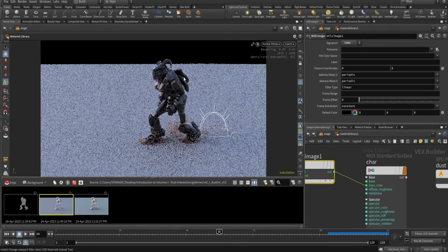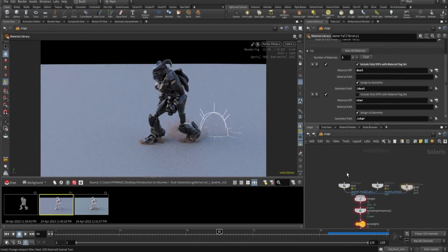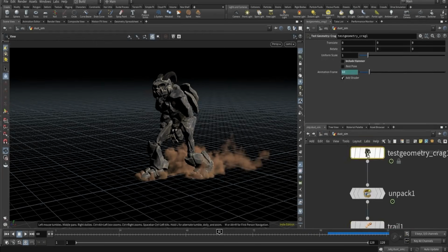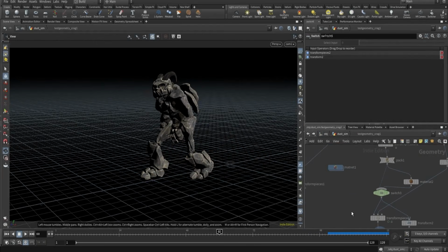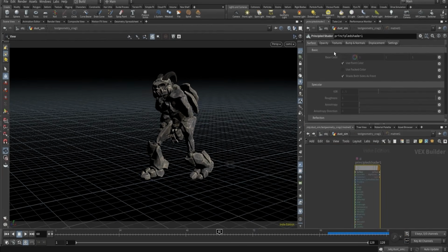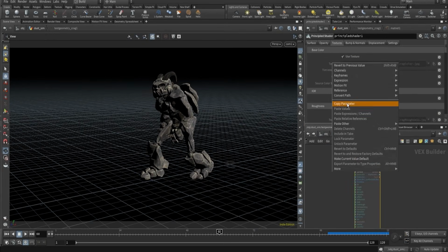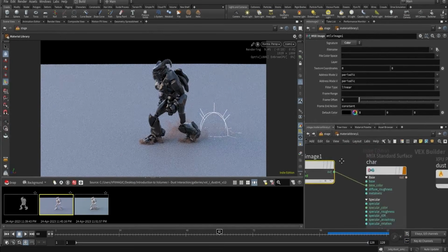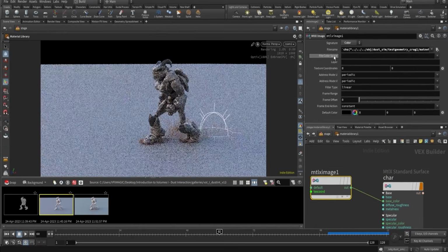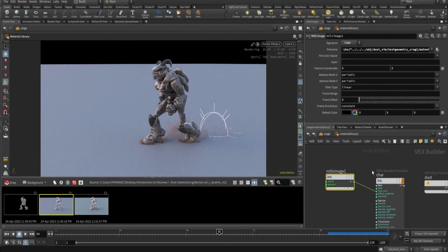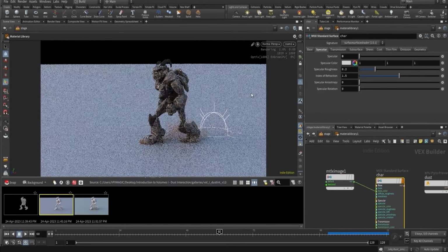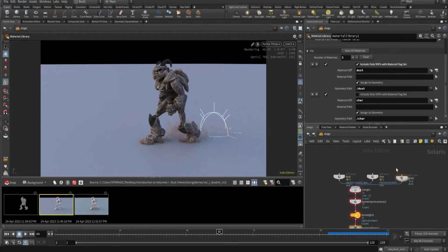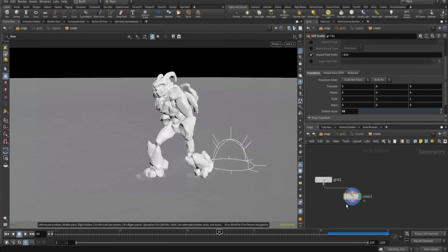So how do I find out the texture of this one? So it is already there with the geometry itself. So if I go over here and if I dive inside, as you can see, it's using some SOP already. So I'll just go to this texture, copy this path, back in stage, and I'll just paste it over here. It's reading that texture. I have that texture now, right? That's what I want.